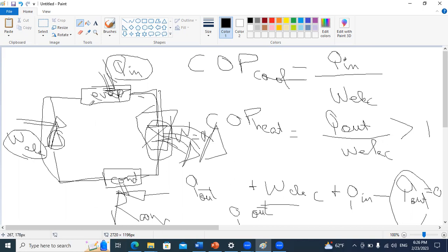And in this case, as we mentioned, what is useful will be the work at the turbine level. So W turbine is the work I want to produce at the turbine level. And in general we need to consider the net work, because we can use a part of the work of the turbine to operate, let's say, the compressor.